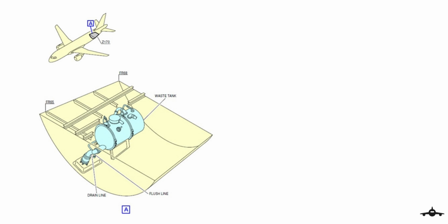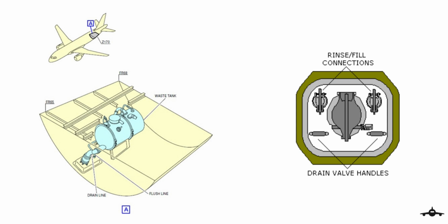Almost all aircraft have toilets at the back of the aircraft. All wastewater is collected into the waste tanks, which for a narrow body aircraft like the A320 can be up to 200 liters. The drain line and flush line from this tank are carried out to the outlet located near the tail of the aircraft, which is used by the lavatory service equipment to connect with the aircraft.